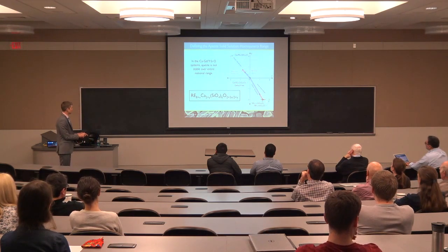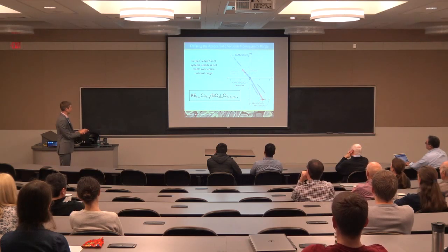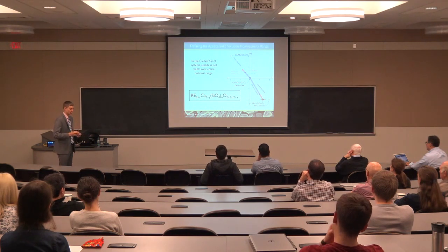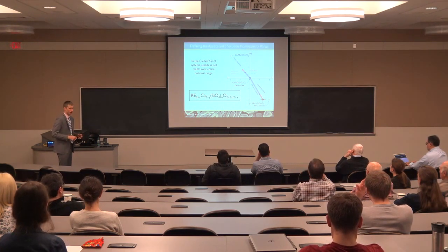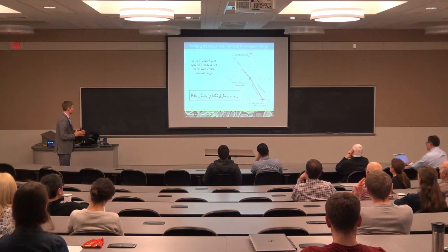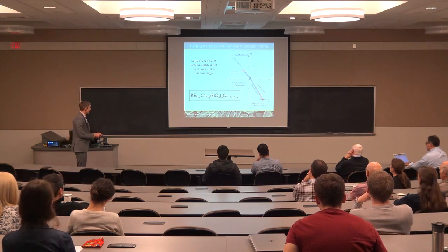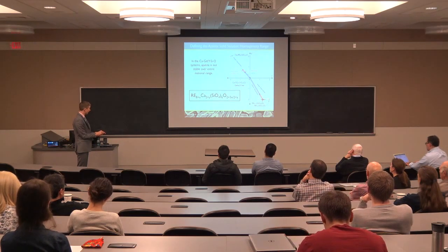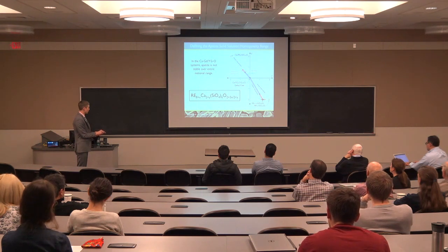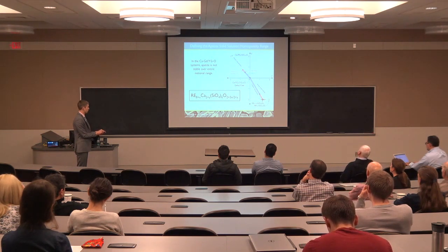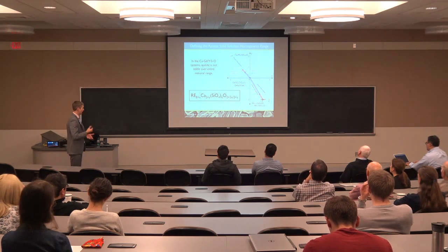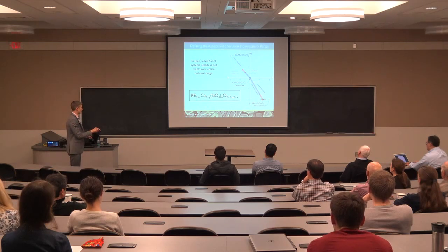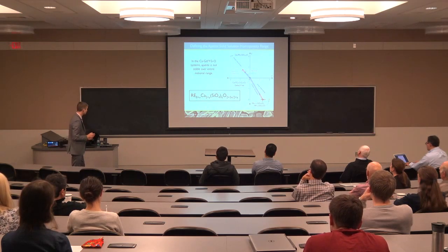And what we found down here, first, is that the gadolinium system covers a wider range of compositions. This is consistent with thermochemical data that shows that the gadolinium-based apatite phase is more thermodynamically stable than the yttrium-based phase, a wider range of compositions. And at this end, we prepared apatite or two-phase mixtures on both sides of what this range would represent, and we find that they both fall pretty closely here. So we could use that insight to say that it's probably this cation vacancy mechanism that allows the apatite phase to be stable rather than this anion interstitial mechanism.